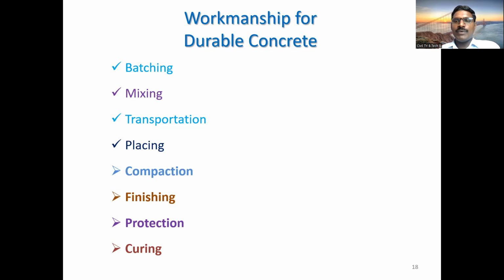If you vibrate the concrete, the air voids will be removed or reduced. So compaction is again very important. Then finishing: if we de-shutter the component and some finishing is required, we have to do that. Then protection. We should protect the concrete, and curing is a very important factor which affects the durability of the concrete.